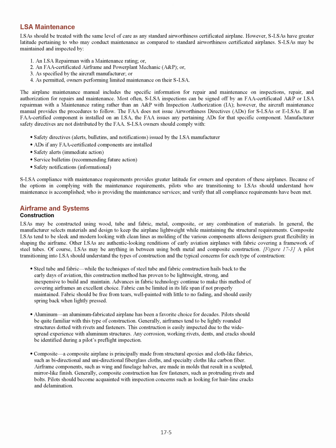LSA owners should comply with safety directives, alerts, bulletins, and notifications issued by the LSA manufacturer. ADs, if any FAA-certificated components are installed. Safety alerts: immediate action. Service bulletins: recommending future action. Safety notifications: informational.